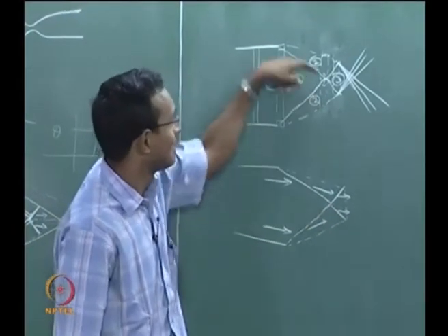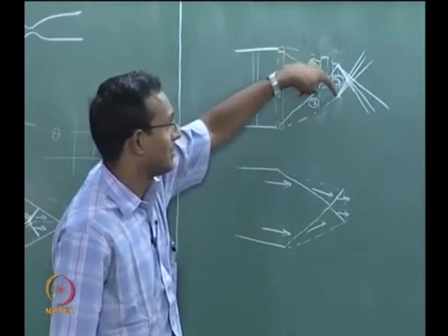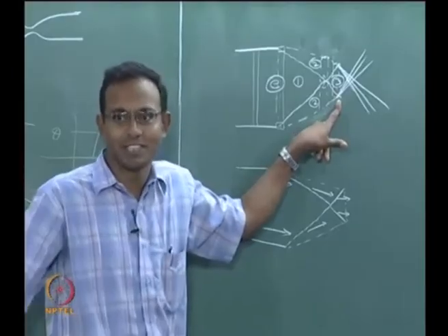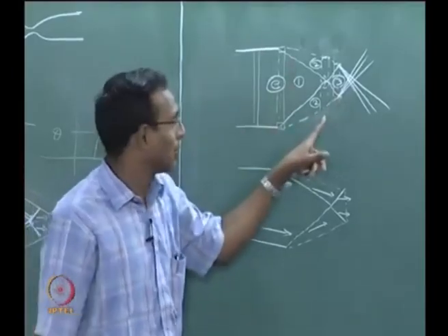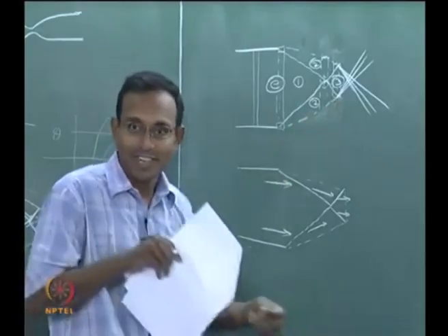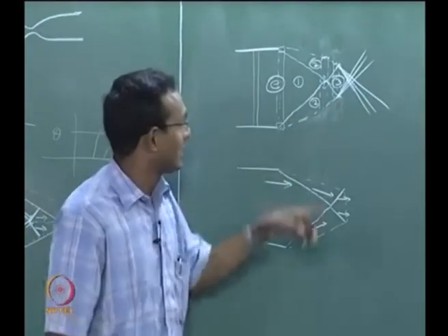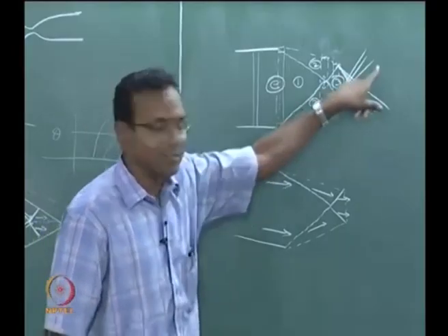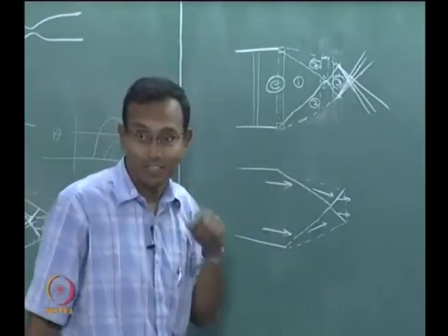One way of looking at it is the compression wave comes here and sees an adamant atmospheric boundary condition which says pressure cannot be changed. So the boundary is going to replace the compression wave with an expansion wave at that point, so that the compression and expansion get cancelled. At that point alone they will be cancelling, everywhere else it is going to continuously expand. That is one way of looking at it.